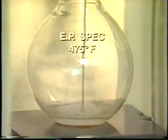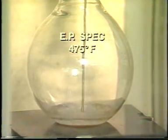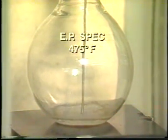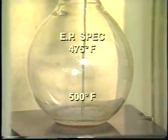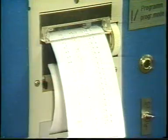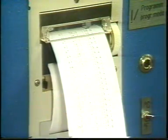Here is a sample with an end point specification of 475 degrees Fahrenheit. If the sample boils away at this temperature, the product contains the right proportion of heavy components. The actual temperature, however, at which the last of the sample boils is 500 degrees Fahrenheit. Since heavy material boils at high temperatures, the product in this example contains too many heavy fractions. Some distillation products are given a boiling range test. A boiling range test identifies both light and heavy components over a product's entire boiling range.